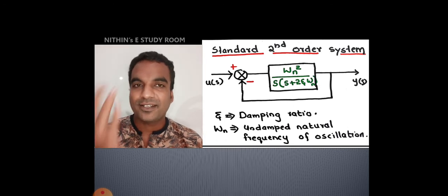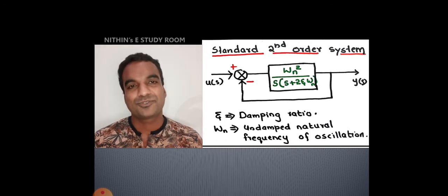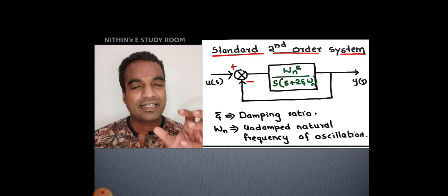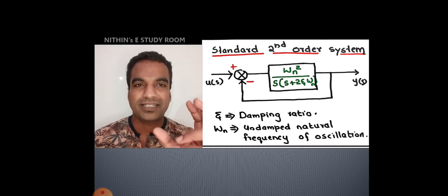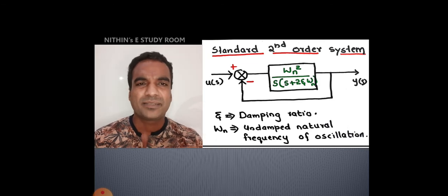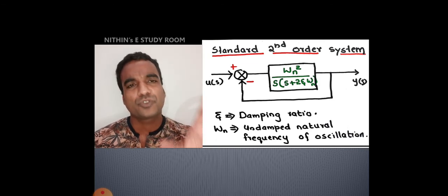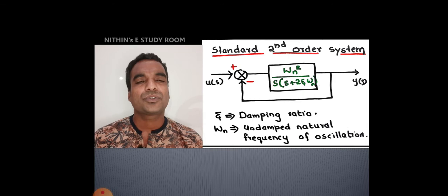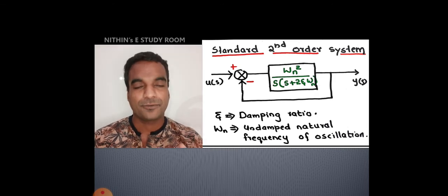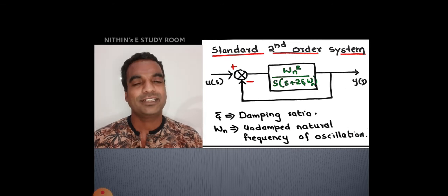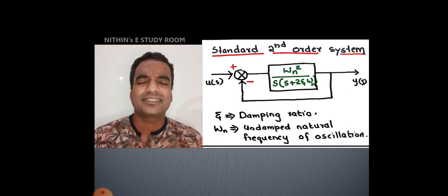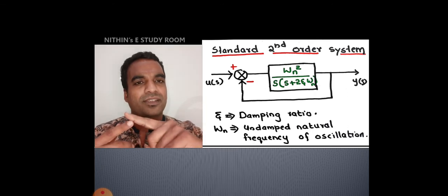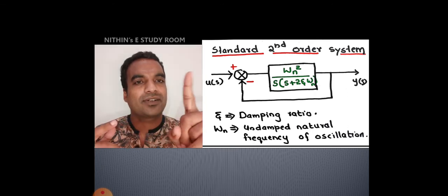I think everybody has completed measurements. There should be some elements like a spring, a mass damper, some air damping, some eddy current damping. Such a system should be there in order to increase the friction and limit the oscillations. Otherwise, if there is nothing like spring damping or eddy current damping, what happens? It will go to 2, but it never stops at 2.